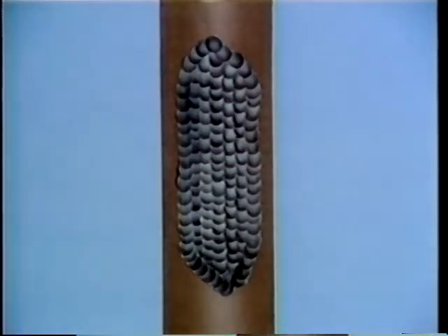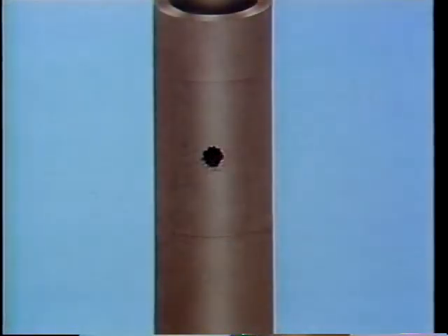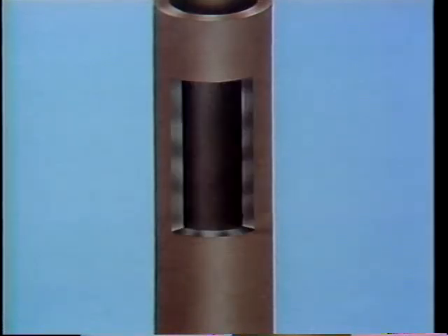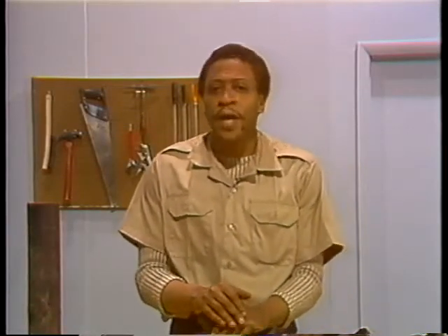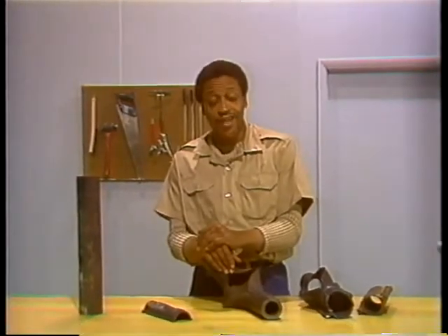If there's a rupture in a tube, it can sometimes be repaired by forcing it closed and welding it. This type of repair is also clad to increase its strength. If a rupture cannot be closed, it's sometimes possible to perform a window repair. In this repair, the damaged area is cut out and replaced with a new piece. Selection of the type of repair will depend on the type of failure and the amount of time available to fix it. We'll see exactly how these repairs are performed in a few minutes, but right now take some time to go over the material on tube failures and deformities in your text.